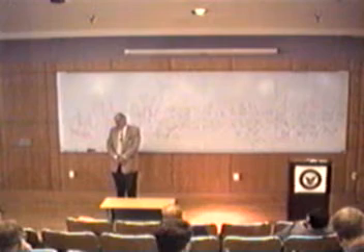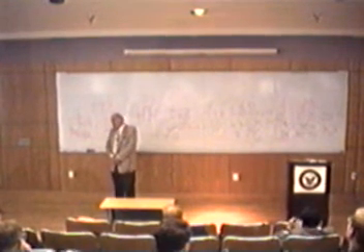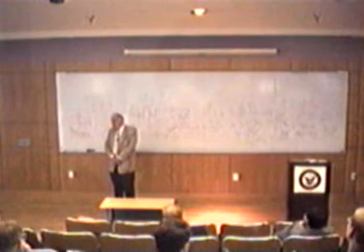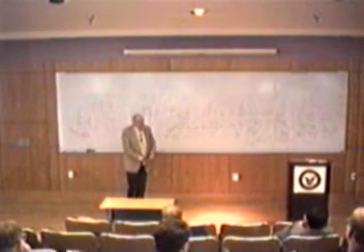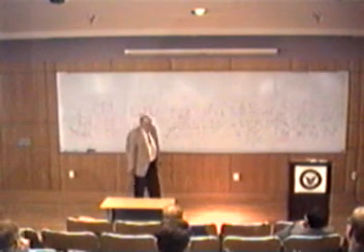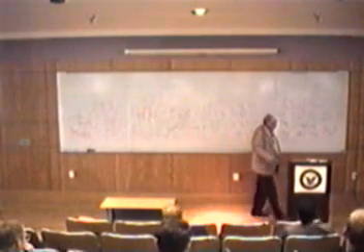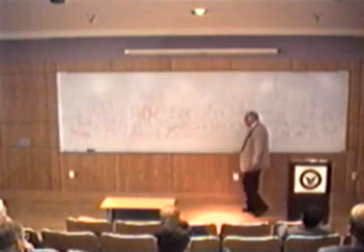I told you in the very first lecture on digital filters how the guys who were analog people tried to stick to the analog approach and think the digital one was the same. They were wrong, completely wrong. They could not take a constant input and hang on to it without a drift. On the other hand, I can put a 1 in a digital filter and 5 years from now it's a 1. You put a 1 ohm resistance in an analog filter and tomorrow it isn't 1 ohm. It's changed. Furthermore, they had heating effects and they had other things. A digital filter doesn't have those troubles.